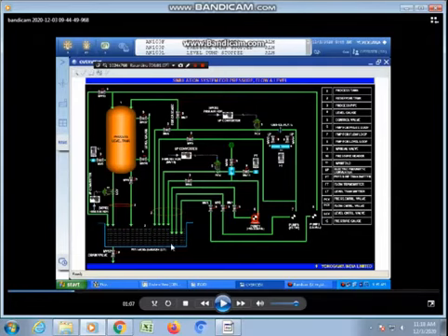The second loop is the flow control loop, where the water is taken through the flow pump. There is a safety bypass for the water flow. Then we have an orifice plate. Before and after the orifice we have the feeds, which are taken through a differential pressure transmitter. From this the water is going to the main tank. The water flow is also maintained through a final control valve.